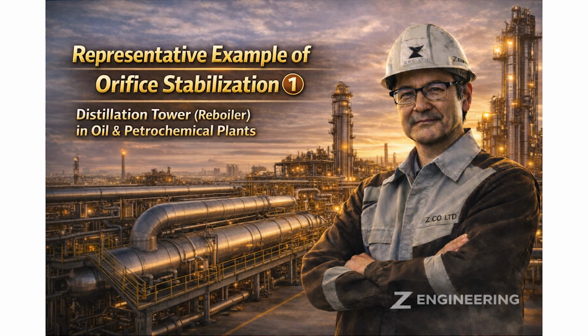First example, a distillation column in a petrochemical plant. In this case, steam consumption and differential pressure are almost constant. The plant operates 24 hours a day. There are no process changes. Temperature is stable. Flow rate is stable. Steam usage is nearly constant. In reality, condensate generation changes less than 10%. Under these conditions, an orifice trap works perfectly.